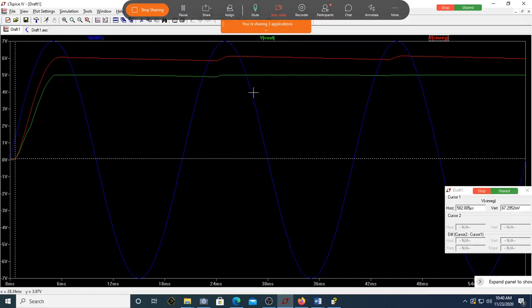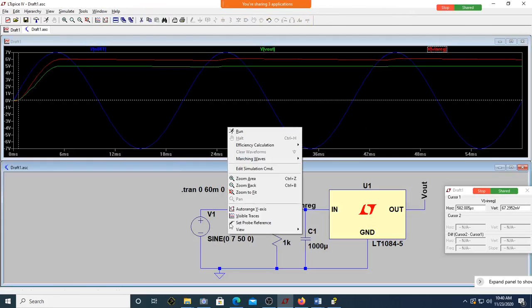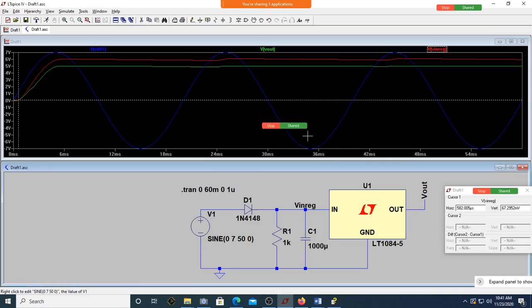So how do we overcome that? We can overcome that by just going for a larger amplitude. So I can make the amplitude around 10 volt. It's fine. It would have been 12.5, and 12.5 corresponds to 9 volt RMS. That's it. Okay, now let me run it.